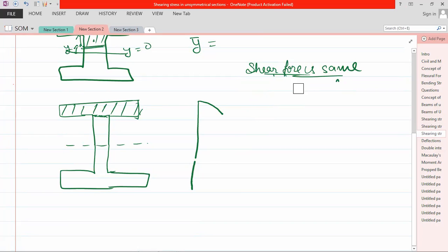It is not area because the other term will cancel out from the bottom I, so it will be tau 1 into b1 is equal to tau 2 into small b2. As you know that this thing is decreased and this one is large, so if you know this tau 1, you know b1, then just divide, and it will increase suddenly at the junctions.